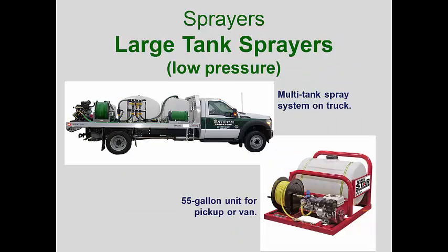Many of the larger landscape management companies obtain trucks that hold 300 to 500 gallon tanks. These are connected to a pumping system that can deliver several gallons per minute at relatively low pressures, something below 40 psi. These systems utilize long hoses that can reach to the back of the customer's yards from the street. Spray nozzles usually deliver relatively coarse sprays so as to avoid making mist that can drift onto adjacent properties. I'm not a real fan of these systems because companies that use them generally spray all of the trees, shrubs, and flowers at the same time, which is definitely not an IPM approach.